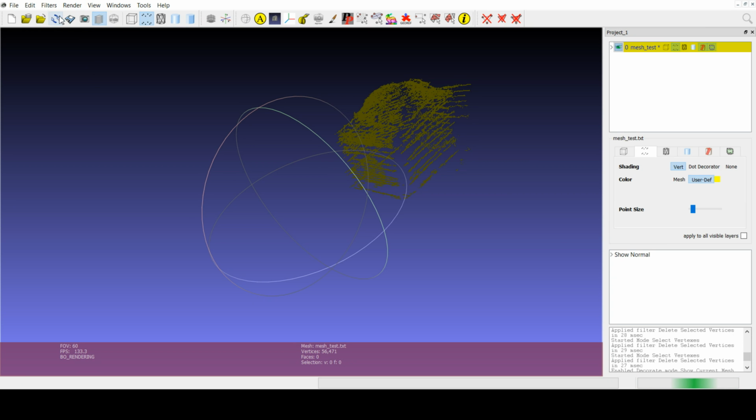First, we're going to do show normal. Then we're going to do compute normal to point set. We're actually going to have to do a pretty high number like 7,500. And we're going to make the trackball center 0, and apply that. This will take quite a while.